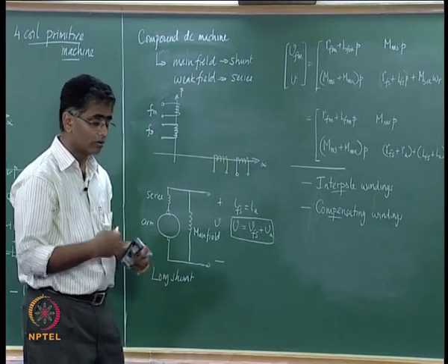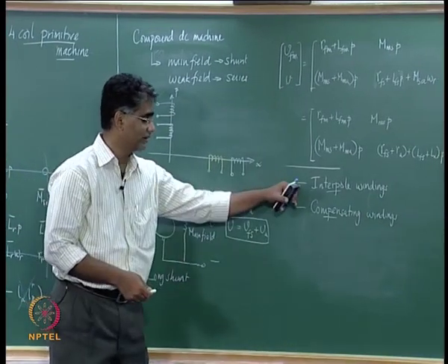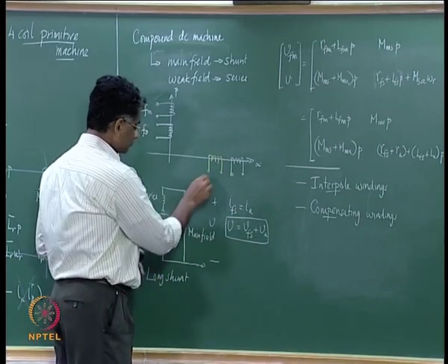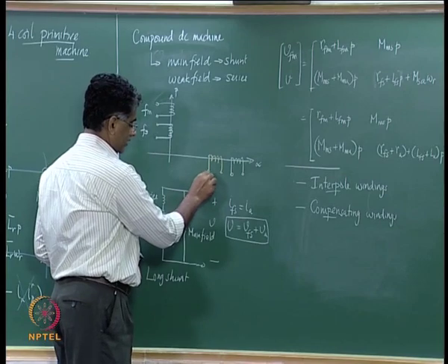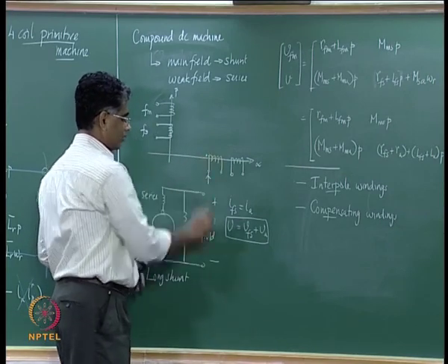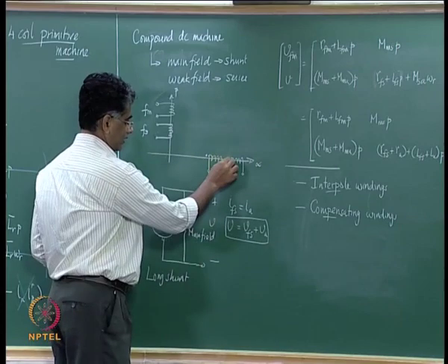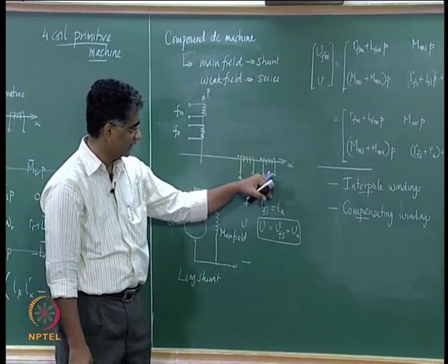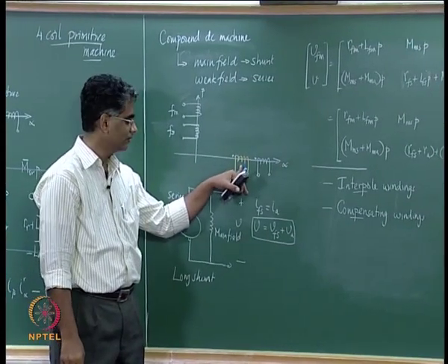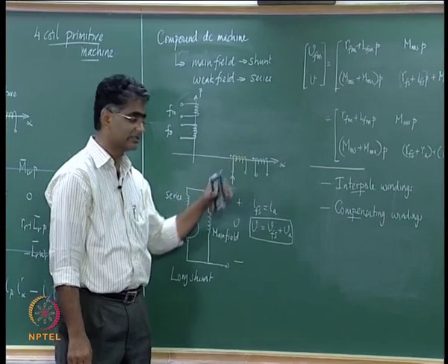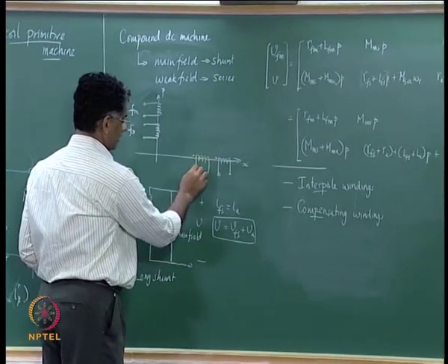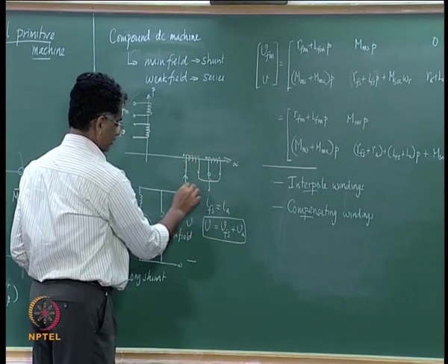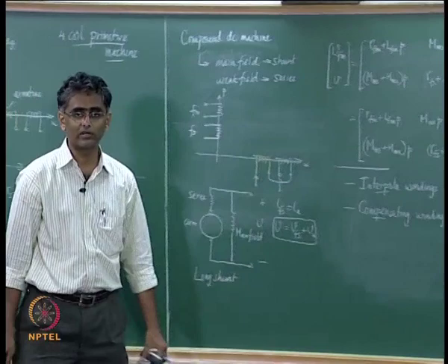which is now going to oppose the armature. They are connected in series with the armature. Therefore, if this is going to be the armature current flowing into this, let us say you have a dot point here, and then this coil has a dot point here. Since this MMF has to oppose the armature MMF, but it has to be connected in series, what one would do is take this here, and this winding is now connected here, this is brought out. So, this is the armature interconnection.